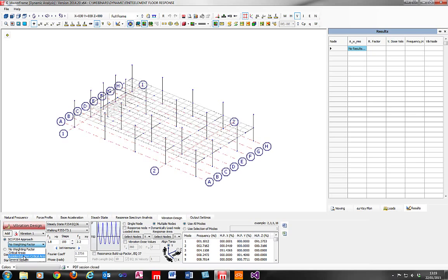I'm going to say that it's a residential non-critical area, maybe with a damping ratio of 3%. This is the codified value of the weight of a single person, which is something you generally don't change. I'm going to say for now that I'm wanting to look at a steady state. I'll talk a little bit more about when to use steady state and when to use transient in a moment or two. And I am interested in a walking frequency type of situation.